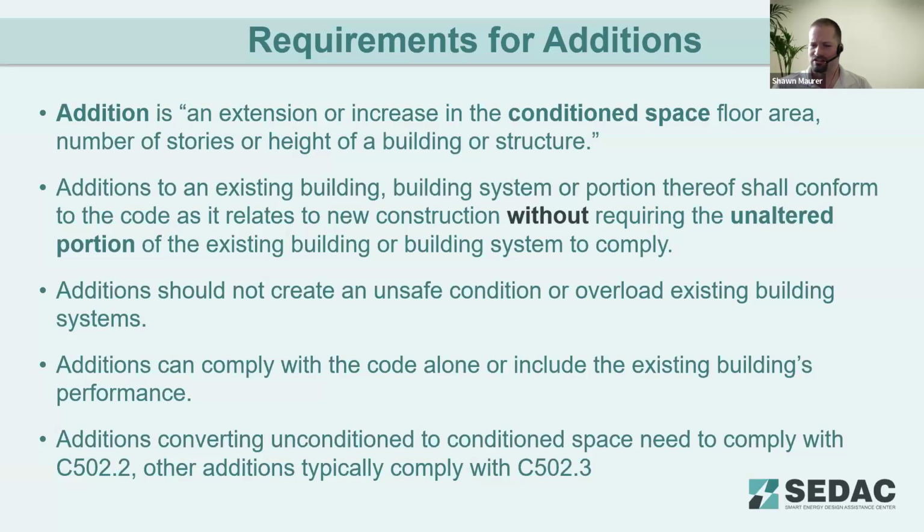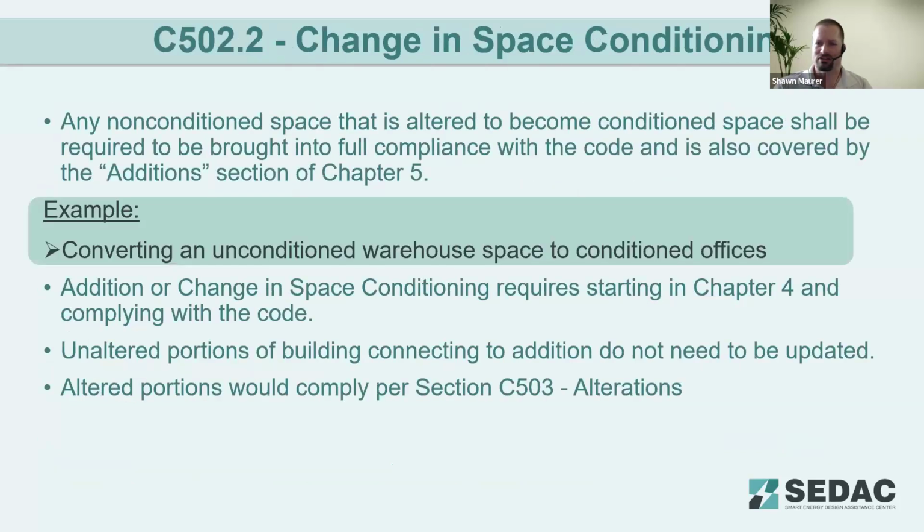Additions converting unconditioned space to conditioned space need to comply with C502.2. Other additions will typically comply with C502.3, and this is where we're talking about a change of use or occupancy versus a standard addition. We'll get into the differences between those here. So C502.2 has some specific requirements.